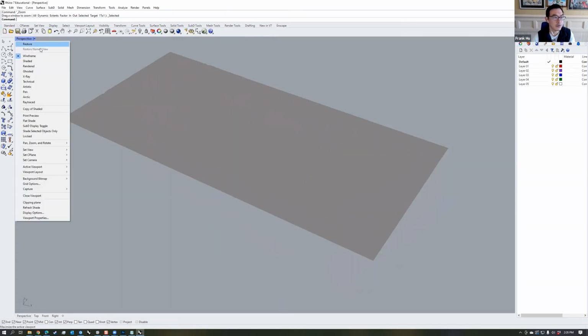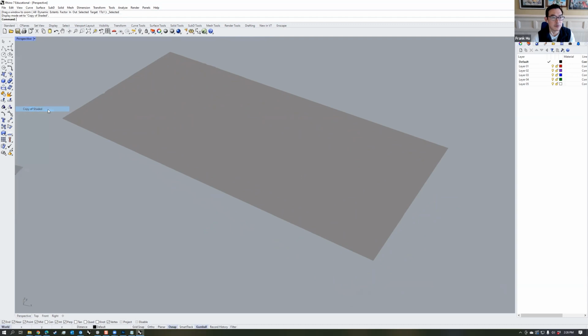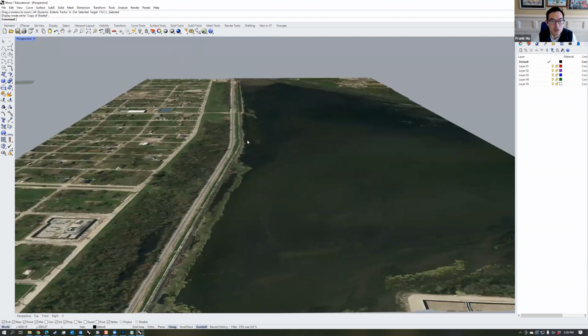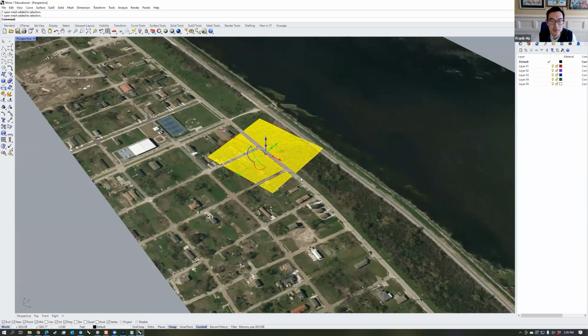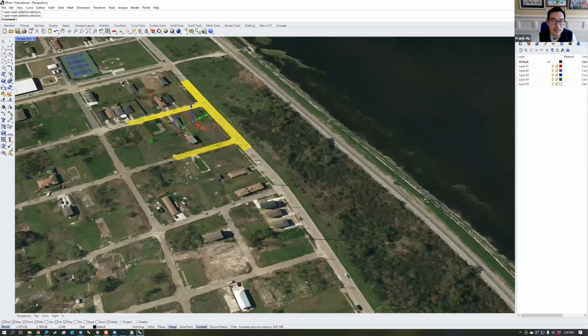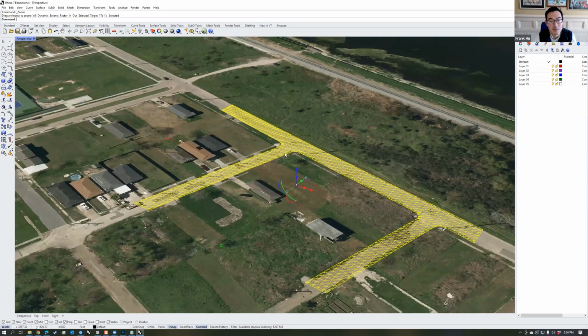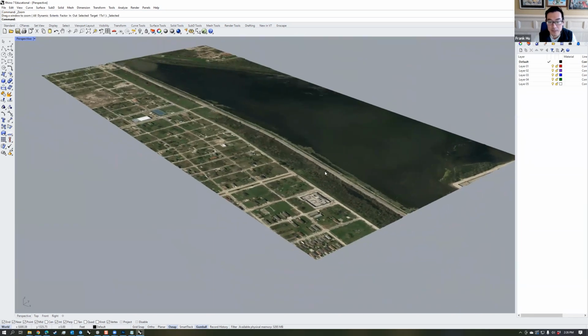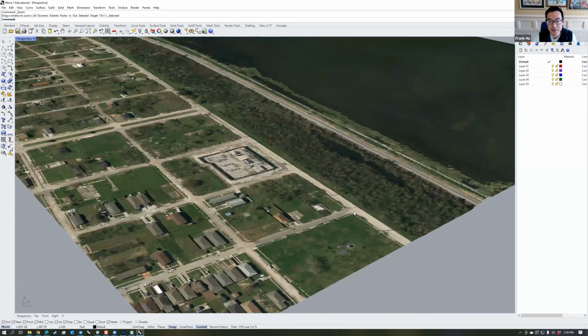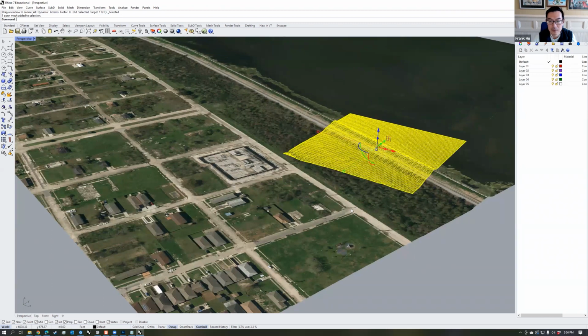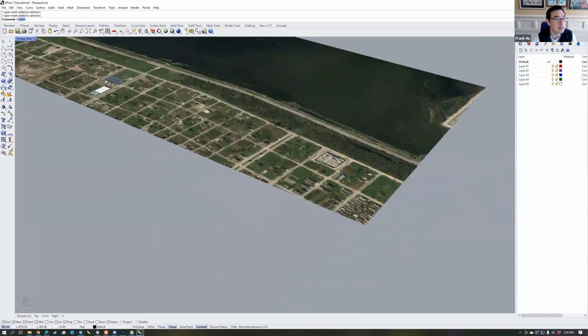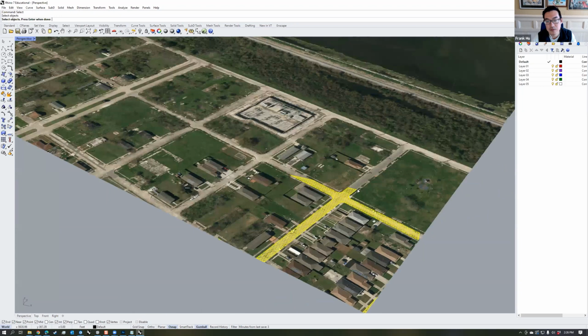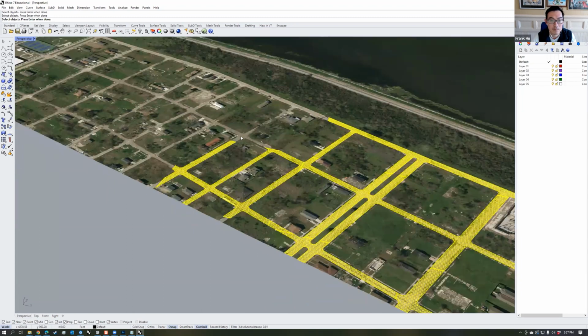You can go to a rendered view, or you can create your own custom view that allows you to view textures. This site turned out to be quite large as one. And you can also see that because we added that road layer in, it comes in as a split feature. There are a few steps you need to do. Number one, organize it into road tiles and just ground tiles. So the first thing I'll do is simply select all the tiles that are the roads.